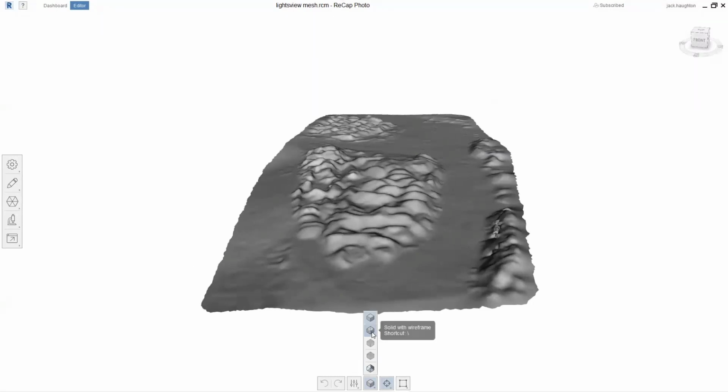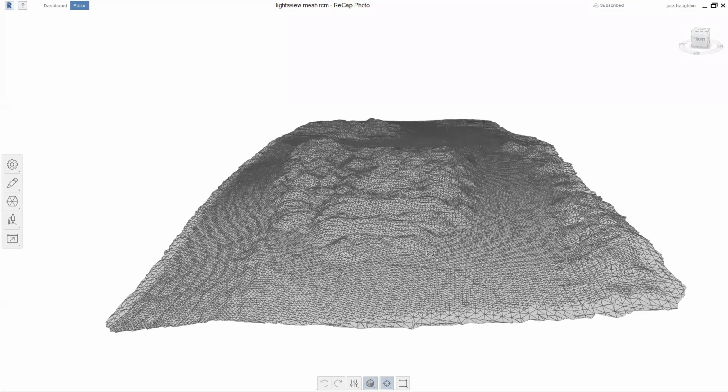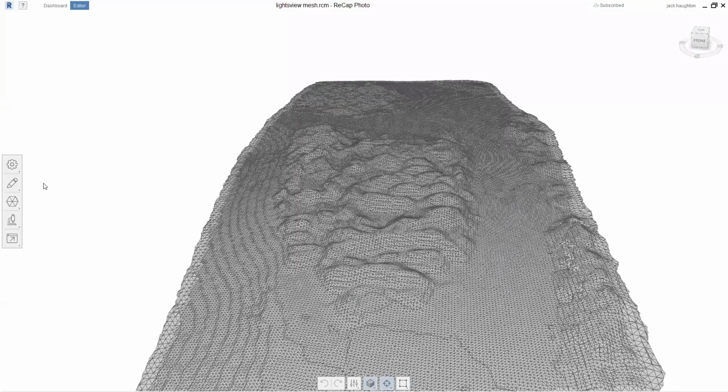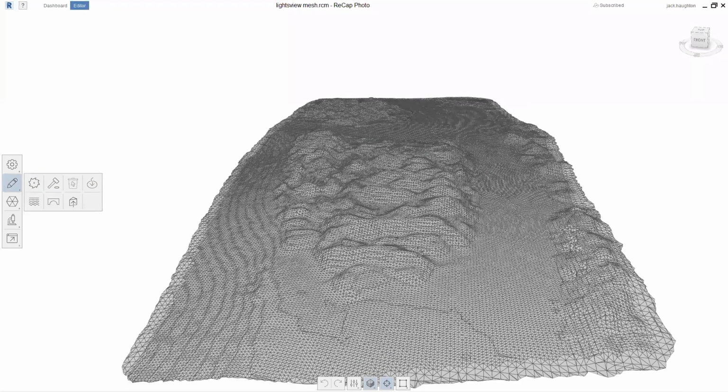Because it's crashed, obviously it didn't get to save, so it's gone back to how it was when we started. Those tools were simply these three in here. Fill holes aims to fill any gaps in your data set. So if I ran the drone over and it missed this section in here, running fill holes would flatten it out and fill in that section, because you would have selected the boundary going around here and it would have found that to be a gap.